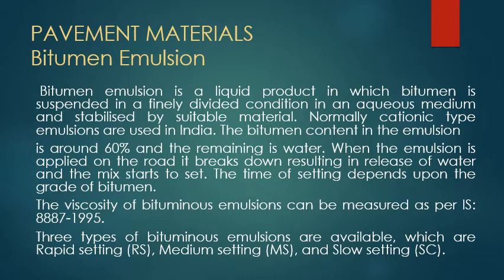These paving grade bitumen and modified bituminous binders need heating before being used in paving application, but cutback bitumen may or may not need slight heating depending on the selected grade of binder and the site temperature during mixing.